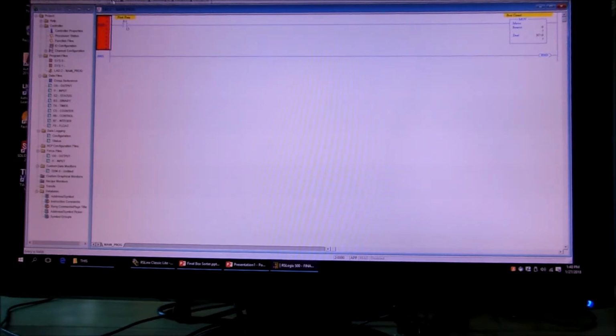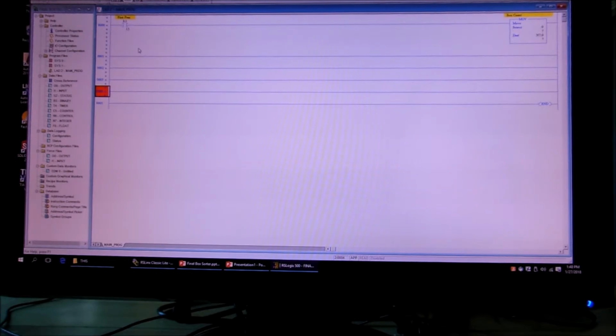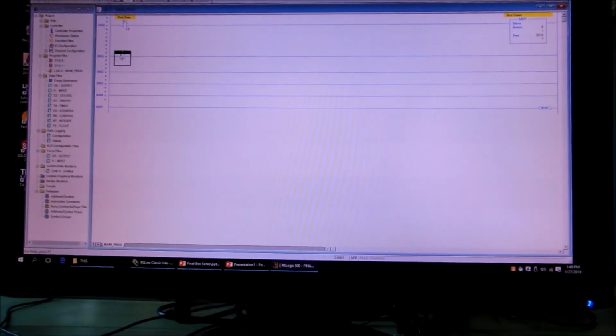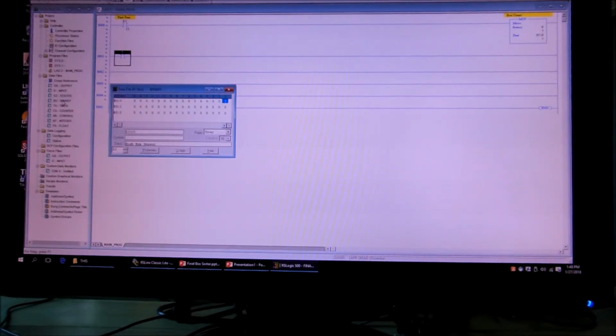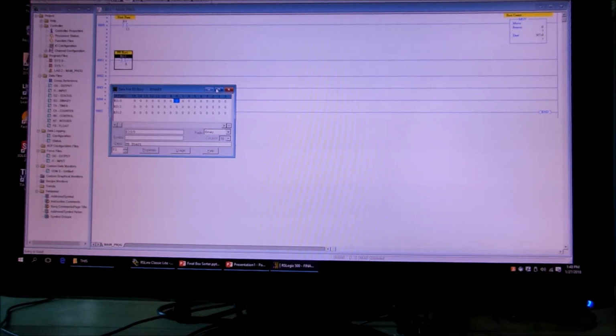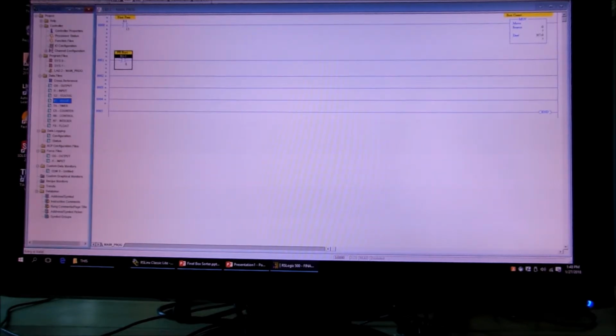And we're just going to add the first few rungs, and then we'll go take a break, and then we can come to the end. I'm not going to show you every rung. It'll take too long, and I don't want to do that. So the first bit we have is bit 8, our start bit for the push button. What we're going to do with that bit is run it through a one-shot, if my program allows me to do that.